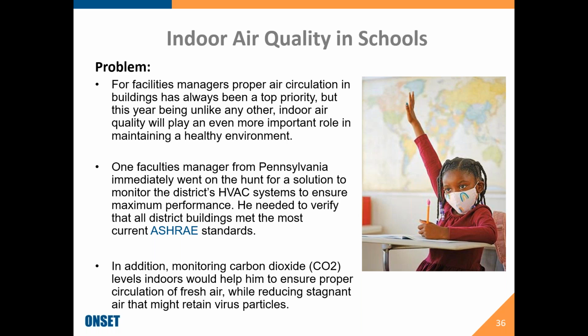And what we're finding is our temperature, relative humidity, and carbon dioxide data logger really fit the bill. We've had facilities managers using these previously to monitor air circulation in the building, but right now it's really helping to determine how effective these HVAC units are so that they can verify meeting ASHRAE standards, that the airflow and the ventilation in the building is the way it should be.